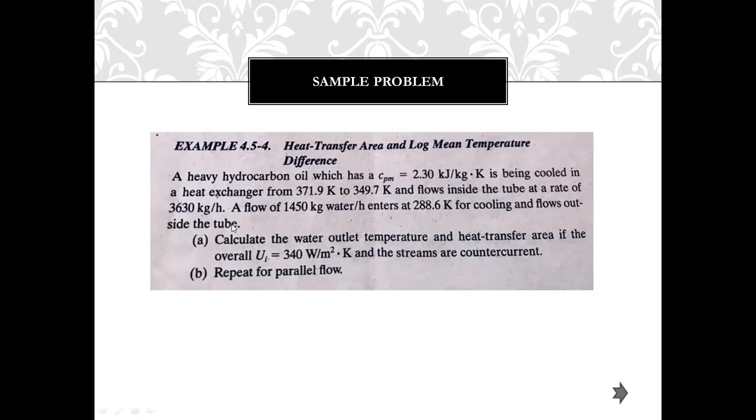the tube. So you can imagine that you have a bundle of tubes, and this bundle of tubes, class, is housed inside a shell. In your shell, you have the cooling fluid, and inside the tube, you have this hydrocarbon oil, which needs to cool down. And for it to cool down, you need this water, your cooling medium, that flows in the shell, in the annular space between the shell and the bundle of tubes, so that this particular hydrocarbon oil will cool